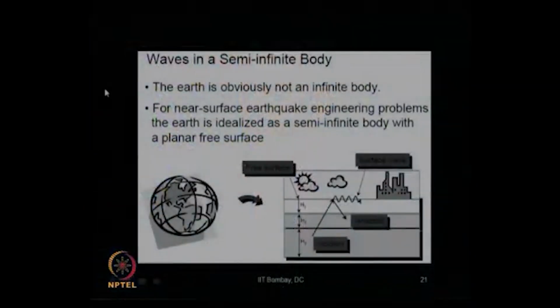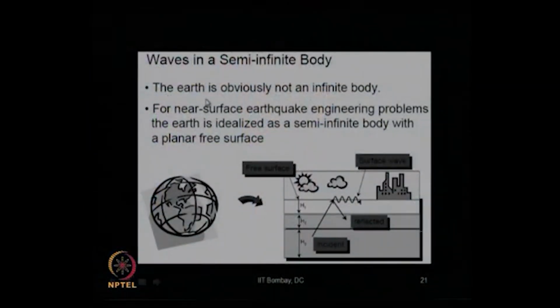So, let us look at the slide over here. The earth is obviously not an infinite body, because when seismic waves start and propagate from the hypocenter or the focus of the earthquake, they travel and slowly come to the ground surface. When they reach the ground surface, they come to a boundary. So, we have to consider the stress boundary conditions instead of considering the infinite body. So, it is a semi-infinite body, as we always consider in soil mechanics and geotechnical engineering problems.